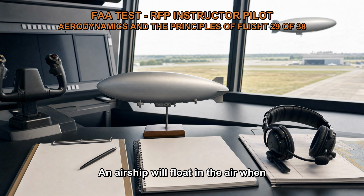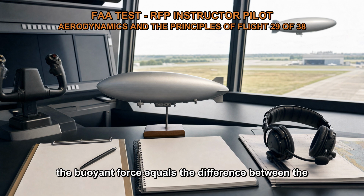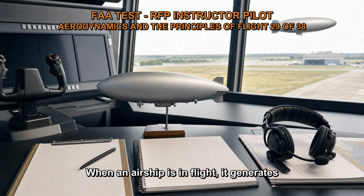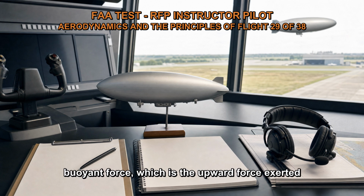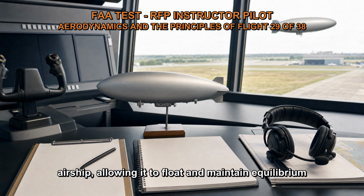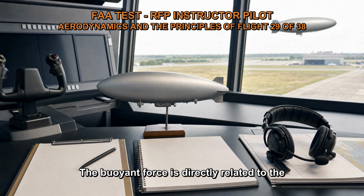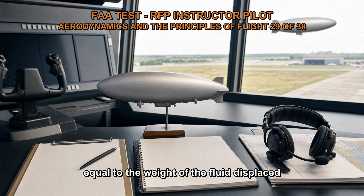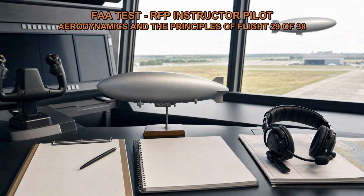An airship will float in the air when the buoyant force equals the difference between the airship's weight and the weight of the volume of air being displaced. When an airship is in flight, it generates buoyant force, which is the upward force exerted on the airship due to the displacement of air. This buoyant force counteracts the weight of the airship, allowing it to float and maintain equilibrium in the air. The buoyant force is directly related to the weight of the volume of air being displaced by the airship. According to Archimedes' principle, the buoyant force is equal to the weight of the fluid displaced by an object. In the case of an airship, the fluid is the surrounding air.